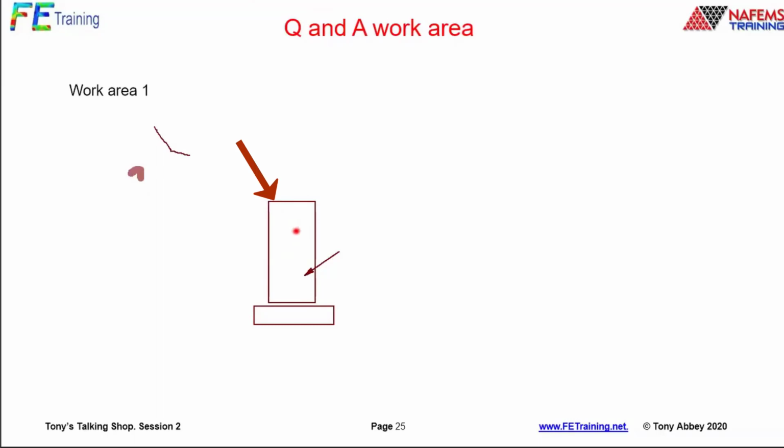So the stress is all down in here. You put a body load in, and so let's say we put 1G in each of the three directions, then the whole structure sees this. All the elements in here see it, and so on. So the idea of doing a unit load case is a good idea. And you're extending that to check the von Mises stress, and you know what you're looking for. That's a great idea.